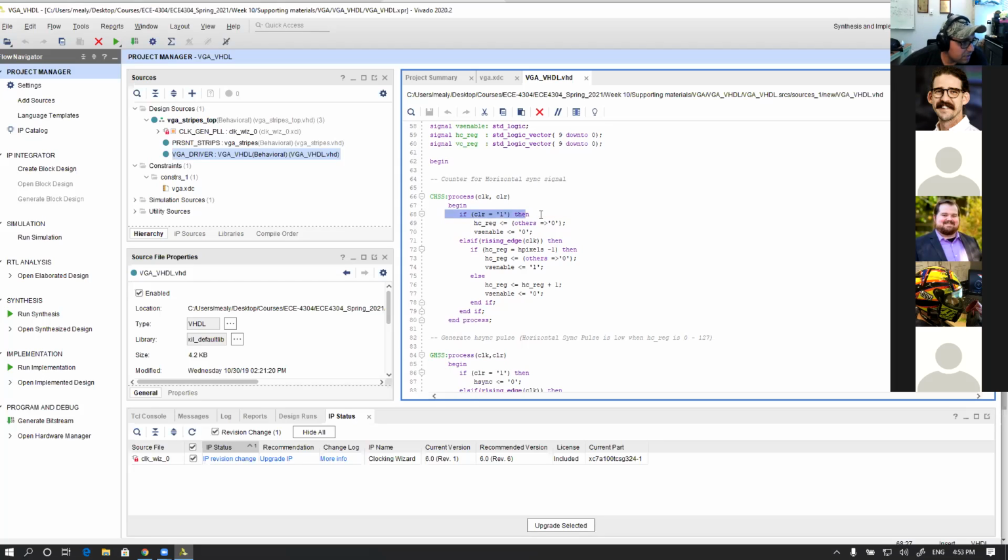So I'm saying that if I'm resetting, basically this is an asynchronous reset. Do you guys agree? Is it synchronous reset or asynchronous reset? Asynchronous. You can make it synchronous, it's up to you. How can we make it synchronous? Move the reset check inside the rising edge check. Exactly. See, now we are just using whatever we learned from VHDL, right?